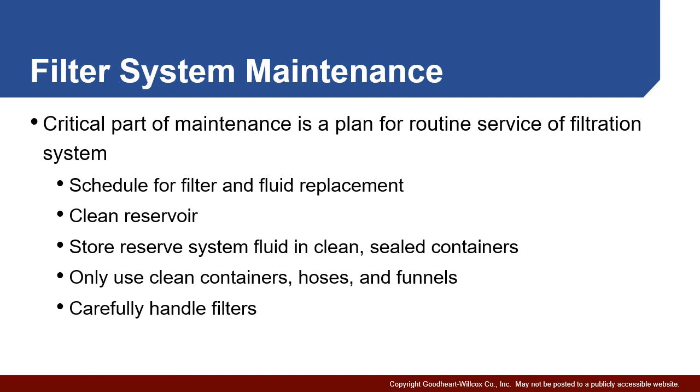So as I said earlier, filtration is critical to the overall maintenance of your system. And to do this, we're going to develop a routine maintenance plan in most industrial environments. Things that need to be done on a regular basis are that the filter needs to be replaced and the hydraulic fluid, keep in mind, breaks down. When you're doing that, you're often going to clean the reservoir. You will have solid contaminants at the bottom, water at the bottom, etc.